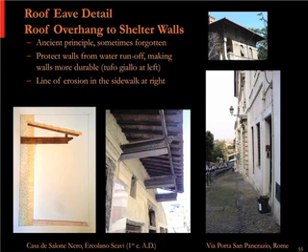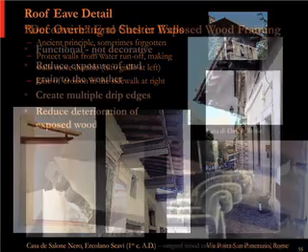Overall, this is serving a great function of sheltering the wall from rain, and that's a principle we can really see throughout history and throughout Rome. At Ercolano, again, the 1st century AD, look at the size of this roof overhang. It must be about 12 feet. That's on a 1.5-story building. There's a section to scale at left and a photo in the center. Again, even that modest roof overhang on Via Porta San Pancrazio, 1.5 feet out, is still keeping water off that facade.